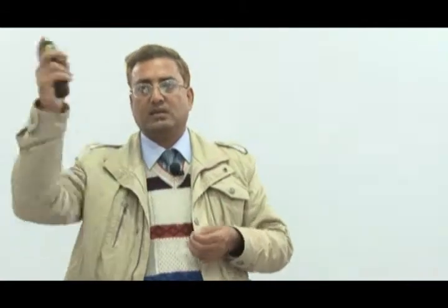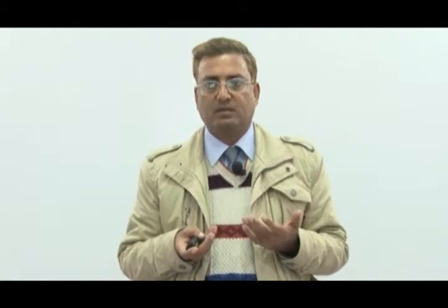And then you require the boundary conditions, that is, the specified displacement on the displacement boundary, and the traction on the specified traction boundaries. So the traction in fact becomes sigma ij nj, where nj is the normal direction. One can see here the two conditions. Then you can go ahead with the stress analysis.